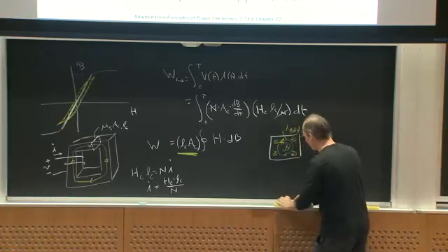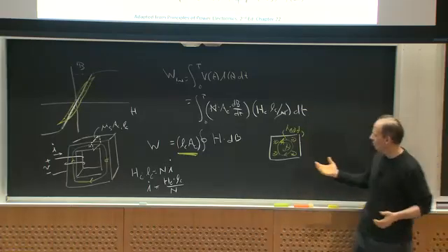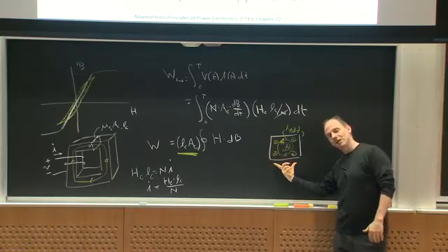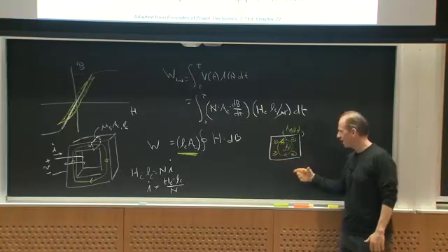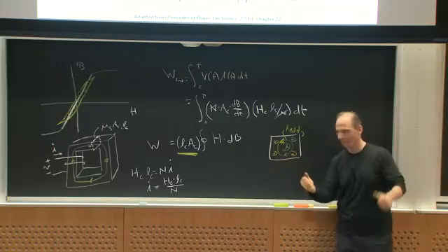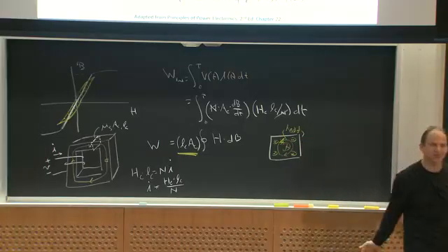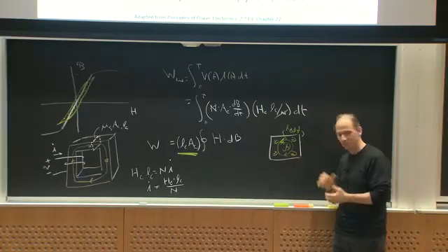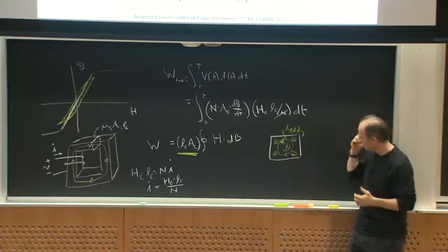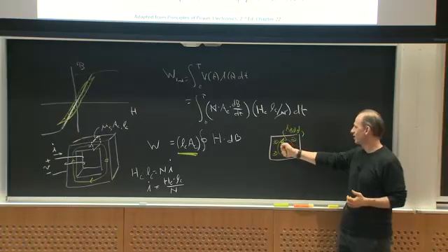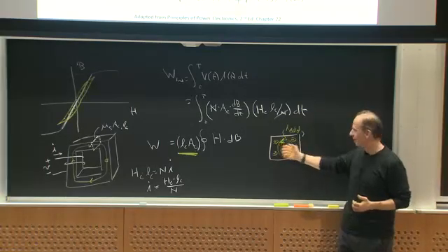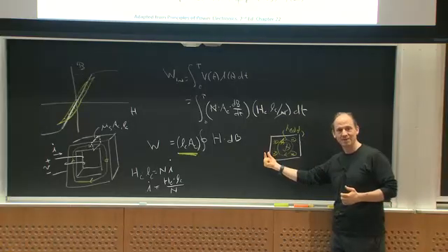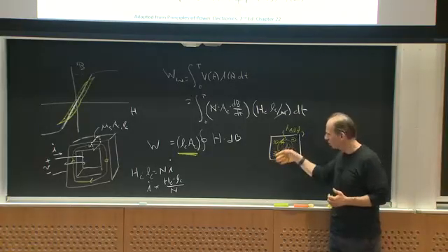When do I start to care about this eddy current loss? I care about it when the dimension of the core is on the order of the skin depth. Right? And if I get a core cross-section that's too big, two things happen. First, I get a lot of eddy current loss, and that just manifests itself as additional loss. And by the way, it scales up with area because I have more room for eddy currents to run around in. So it's not even loss per unit volume. It gets worse as the cross-sectional area gets bigger. But the other thing is, if it's bad enough, it rejects flux from the center of the core, and I might drive up the concentration of flux at the edges and might even saturate it. Right? So what do people do about this?